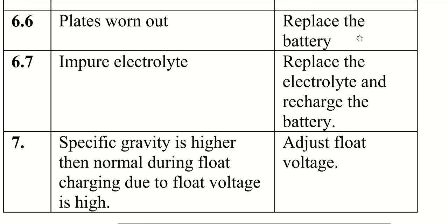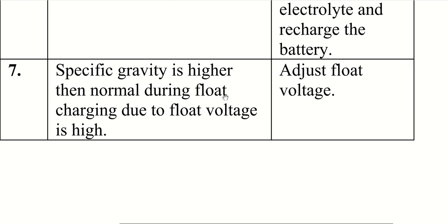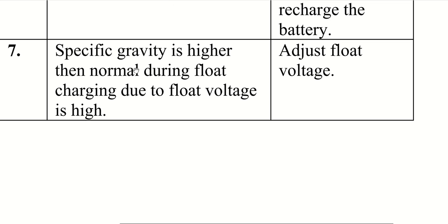Plates worn out: replace the battery. Impure electrolyte: replace the electrolyte and recharge the battery. Specific gravity higher than normal during float charging, due to high float voltage: adjust the float voltage.